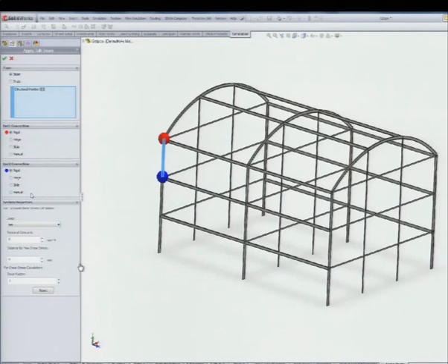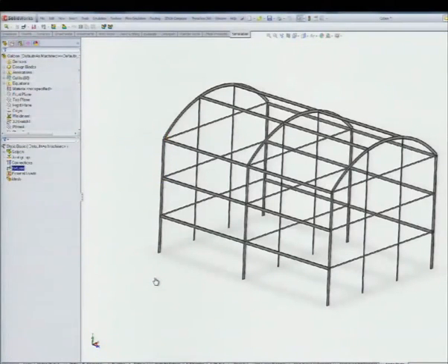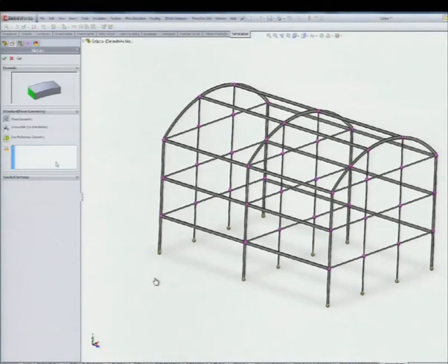The red and blue sphere means that you can select rigid or you can release some degrees of freedom. This is very general. I don't use it too much, but it's important to know. So right now I'm fixing all the boundary conditions at the bottom of the building. I am assuming that the foundation is very rigid.